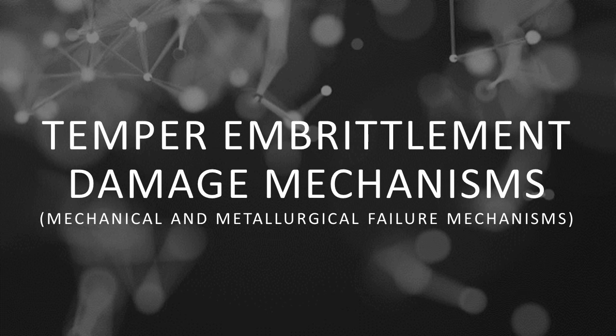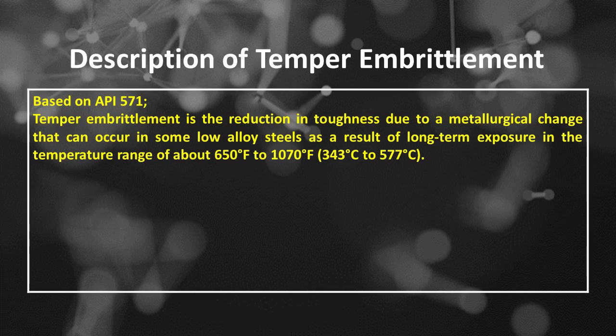Temper embrittlement damage mechanisms is a part of mechanical and metallurgical failure mechanisms. Description of temper embrittlement. Based on API 571, temper embrittlement is the reduction in toughness due to a metallurgical change that can occur in some low-alloy steels as a result of long-term exposure in the temperature range of about 650 degrees Fahrenheit to 1070 degrees Fahrenheit, 343 degrees Celsius to 577 degrees Celsius.